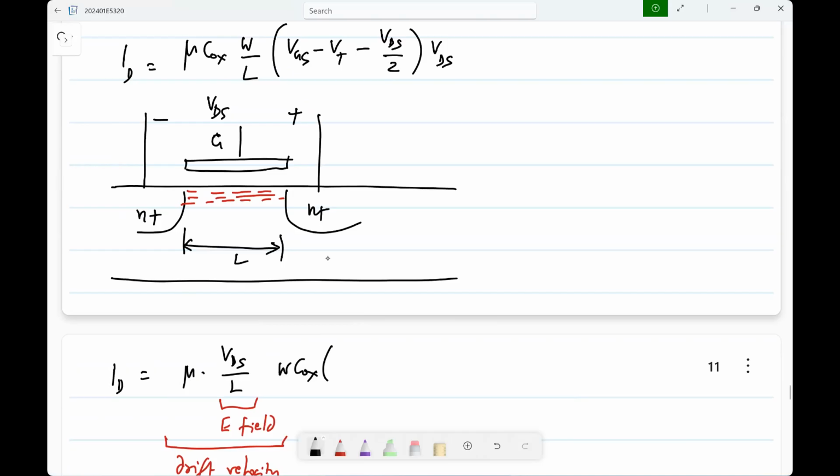So then this times the voltage across the capacitor, right? What is the voltage across this capacitor? It's VGS, I mean, it's that voltage minus VT. That VT comes about because of different semiconductor materials. Although you apply the gate voltage here and the source voltage there, and all these places you will have some other drops, right? That's how you get that VT. VT is the sum of all those extra drops. Okay. So it should be VGS minus VT.